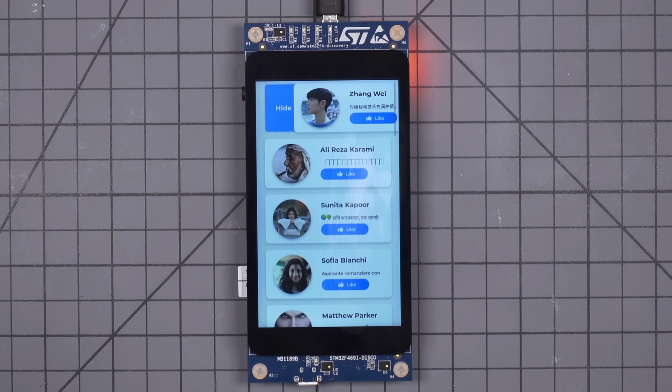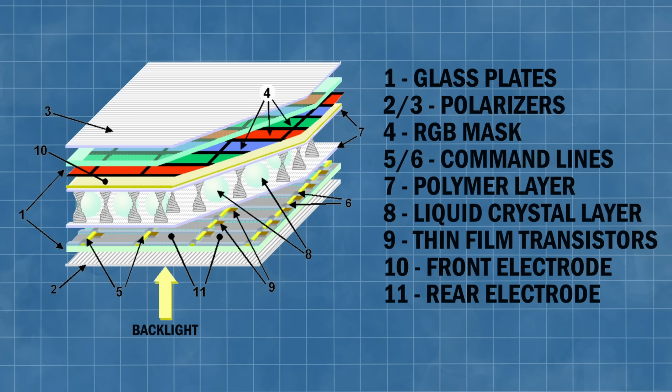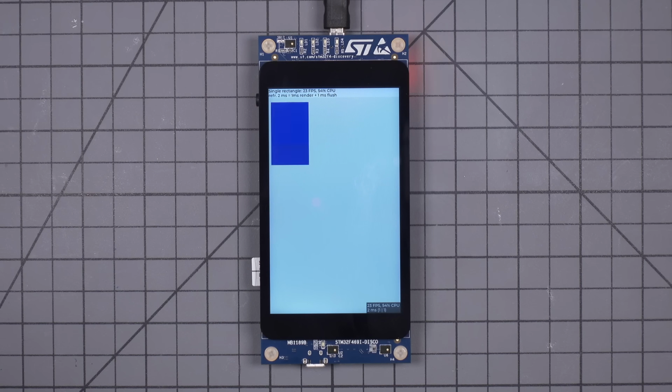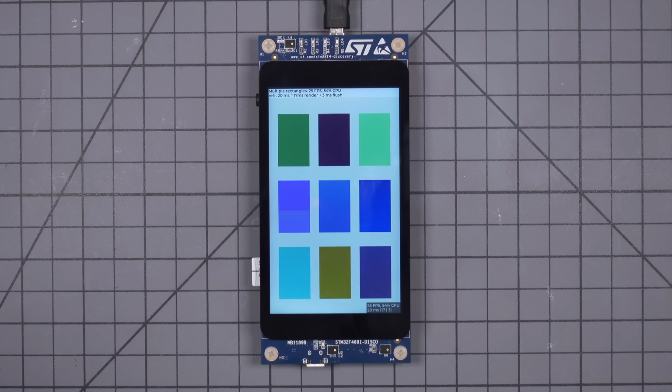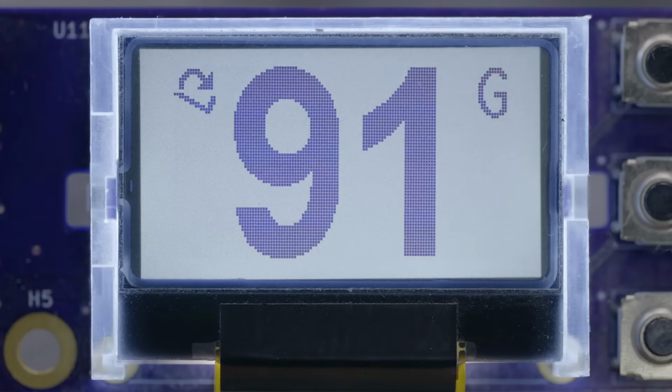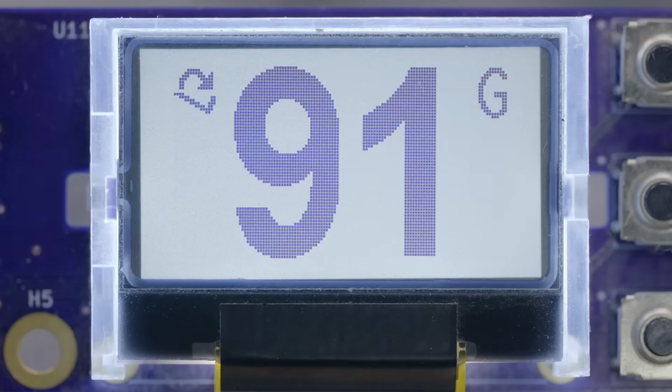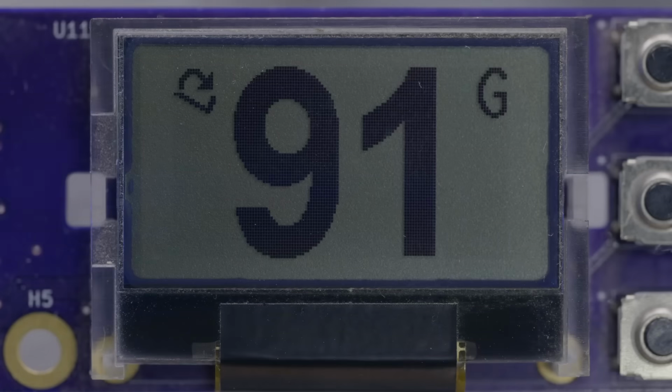The most common type of display is the liquid crystal display, LCD, which works by blocking light. Each pixel of an LCD screen contains a cell of microscopic crystals that change their optical properties based on applied voltage. This is usually a proportional effect, so it's not just on or off, but can vary its darkness depending on how hard it is driven. LCDs do not produce light, but instead rely on backlighting or a reflector to push light through them.